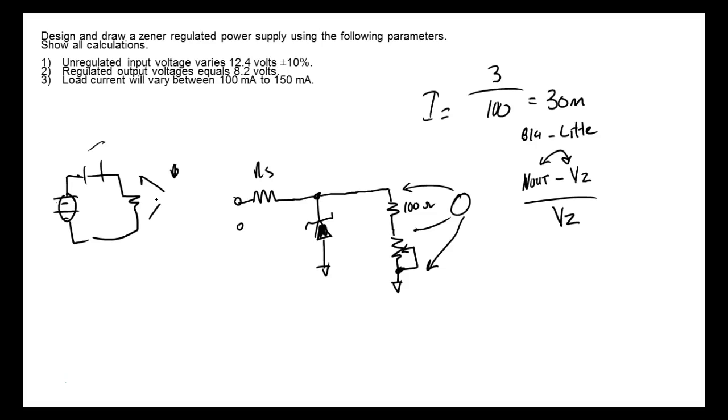So this is what's nice about this. You don't have to worry about everything you do. If you've got a series resistor and I wanted to measure the load current or the Zener current, how could I measure the Zener current? Well, we'd measure the voltage drop across RS, and then I could say IRS would be equal to VRS over RS. Then I could subtract my load current, and that would give you your Zener current.